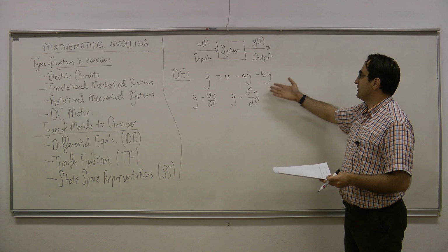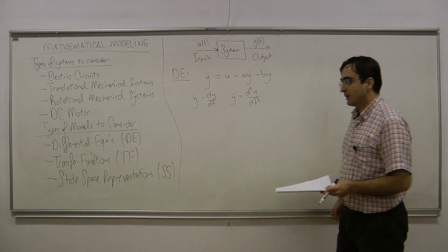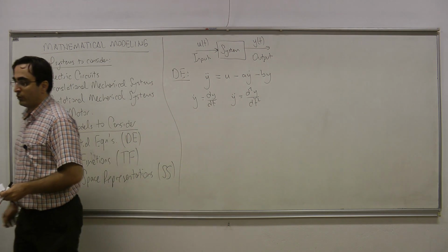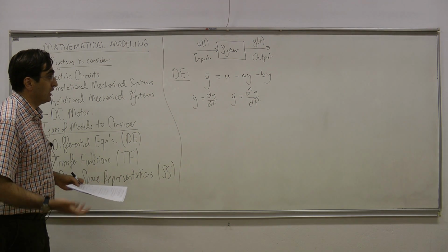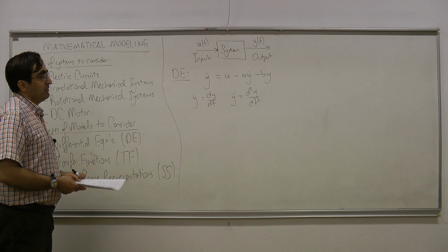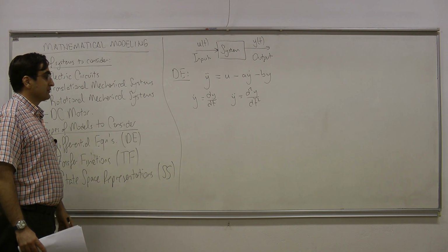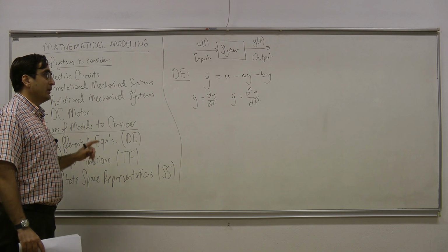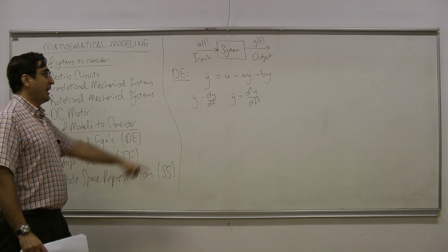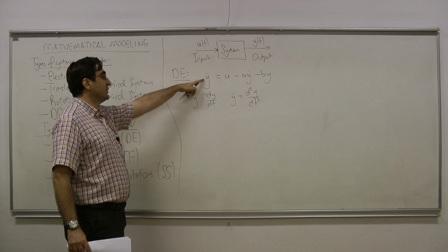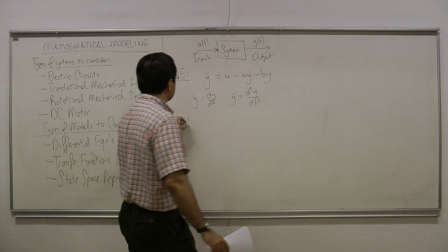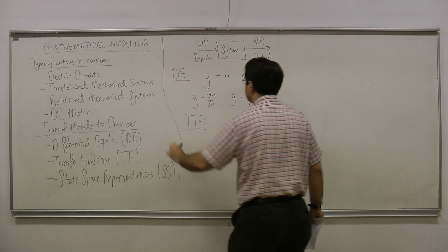this is generally the first mathematical model that we are going to obtain. We are first going to write a differential equation of a mechanical system or an electric circuit. And then we are going to try to obtain the transfer function representation of the system. And this is just going to be passing the differential equation into the Laplace domain. Okay? So let us look at what a transfer function is.